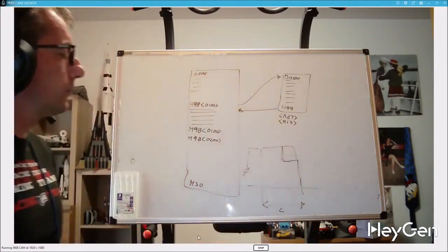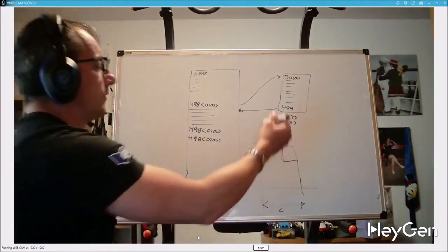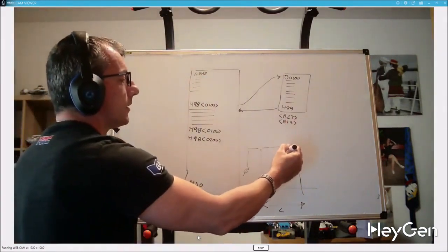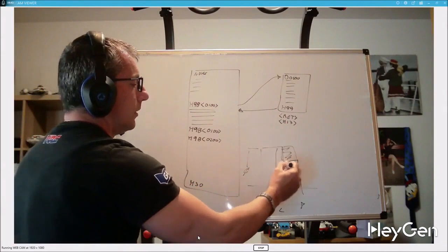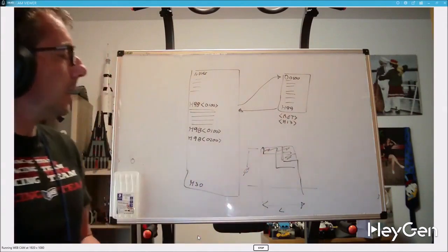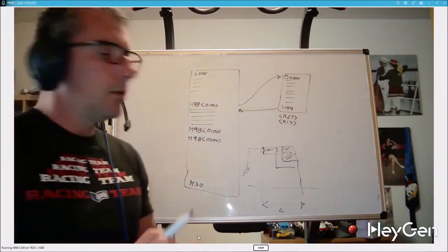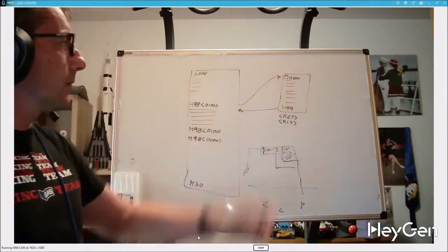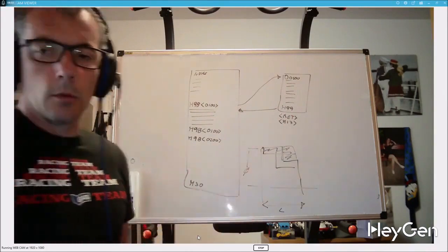So I'll do the chamfering and external turning in the main program, and then I'll create a series of subprograms to handle this hollowing out, which might be done one way this time, another way next time, and so on.